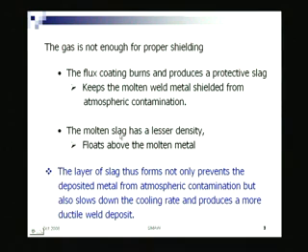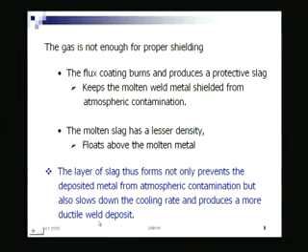So, thereby the slag functions not only in terms of protecting from oxidation and atmospheric contamination, it also helps in a positive sense by making the weld deposit ductile, because it is always preferable to have ductile property than a hard one in such fabrications, right.